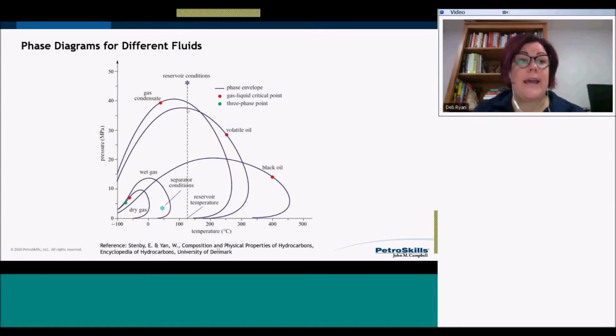What we're doing is we're bubbling gas out in the reservoir before we then bring it to surface, and we'll have more and more of that gas coming out. But it's very interesting and important to note that, again, as we start to bubble that gas out in the reservoir, gas actually moves through our reservoirs much easier than oil does. And again, we're not going to go into some of those methodology or mechanisms today, but that's where we'll often see our gas-oil ratio increasing with time, because what we're doing is, as we're dropping that gas out and the gas is coming out of that oil, the oil's getting heavier and heavier because the light ends are coming out of it, and we're going to show you some of these characterization pieces in a little bit. And that gas is going to continue to increase and flow to our wells, preferentially to oil.